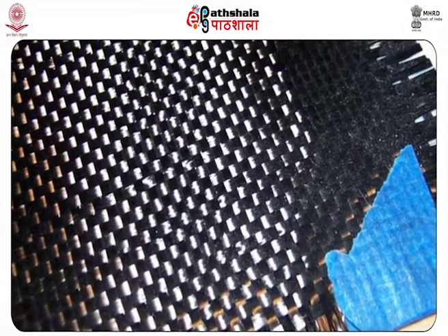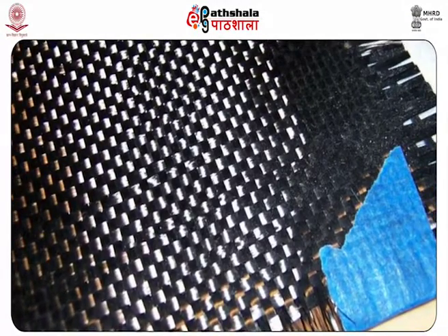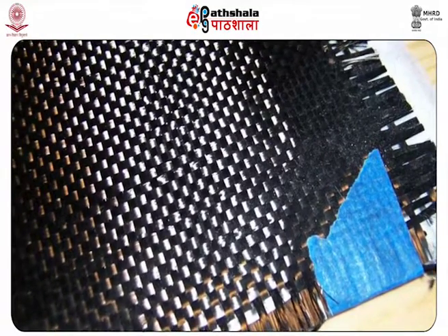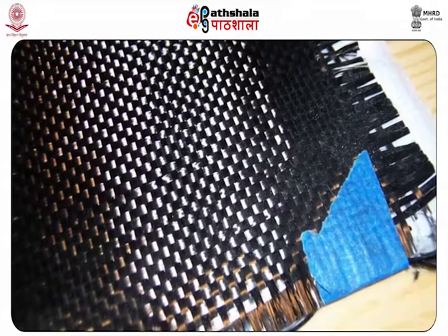Alternatively, graphite fiber or CF is a material consisting of fibers about 5 to 10 micrometers in diameter and composed mostly of carbon atoms. To produce carbon fiber, the carbon atoms are bonded together in crystals that are more or less aligned parallel to the long axis of the fiber, as the crystal alignment gives the fiber high strength to volume ratio, making it stronger for its size.